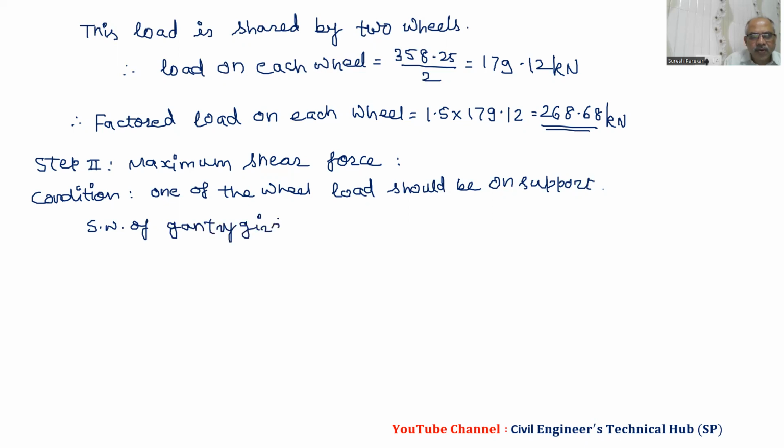And we know for this we have total load upon 250. So for plate girder we are taking it as 200, for beams we are taking 300. So this is a medium load, so we are going to consider 250.